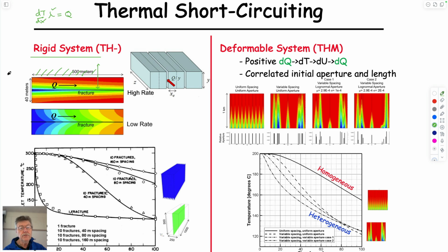This acts as an insulating boundary, and therefore the temperature gradient across here has to be 0. So if you drew the temperature across this boundary as it goes into the fracture, it would look something like this. And on the other side, the fact that this is flat here, this is x, this is t, means that this is a no-flow boundary. So, bottom line, flowing in a fracture, you can make a line of symmetry here that isolates a fracture on each side from the component behavior. This behavior will repeat in all of these units.